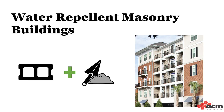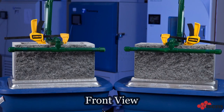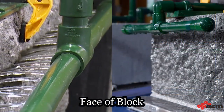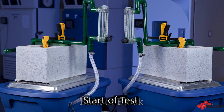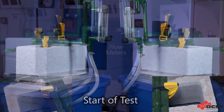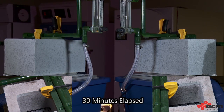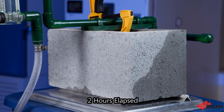Water repellent CMU are usually specified by an architect. To ensure that the CMU is water repellent and promote confidence in the specifier community, many water repellent admixture suppliers have a certification program. The spray bar test is a good certification test. A CMU is sprayed in the lab for 4 hours, and the inside of the unit is examined to see if any water has penetrated. A good water repellent CMU will be virtually dry inside its cores and on the back and sides of the unit. On the other hand, a regular CMU without water repellent will absorb water throughout.